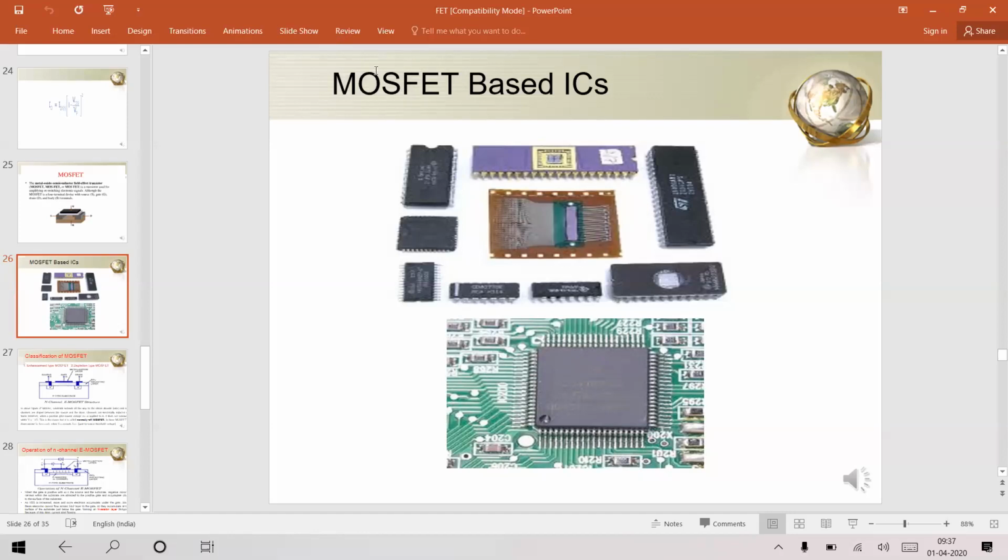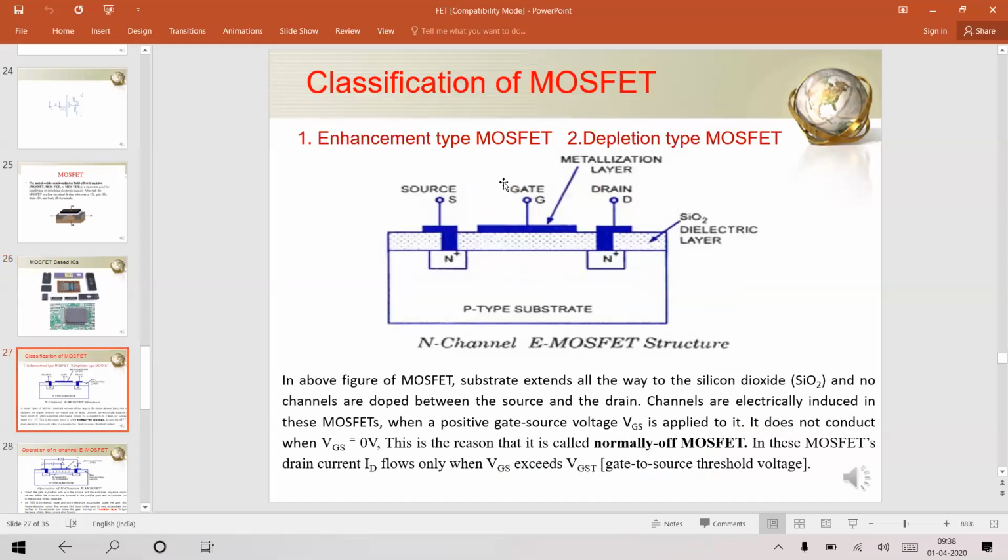So this IC technology is because of this MOSFET till today. Today people call it a FinFET. Today Intel and other companies which are manufacturing ICs use FinFET. Same MOS they replace with Fin. Fin is a structure, how it looks like the fin of a fish. So the device structure looks like that, and the naming is renamed like FinFET. But before that, you had the MOSFET in every IC. So coming to the next slide, operation.